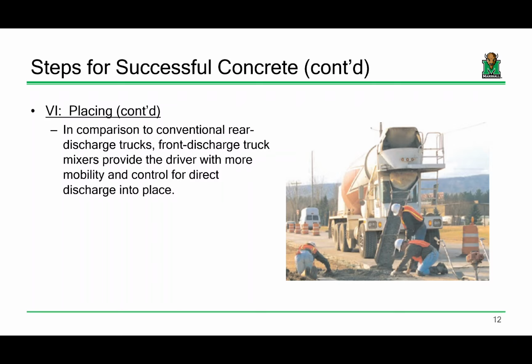So this works. It's really easy. Sometimes you can have access issues, and I'm going to show you a project out in Iowa where you can see how the access would be a little bit challenging. But if you've ever seen a mix truck, you can unfold that end and it can just funnel right out. So, depending on if your truck can get to where the placement's going to be, this might be fine. This would be great for something like a sidewalk placement or curbs where the road's already done, and all you have to do is drive the truck up to it, deposit the concrete, you're good to go.